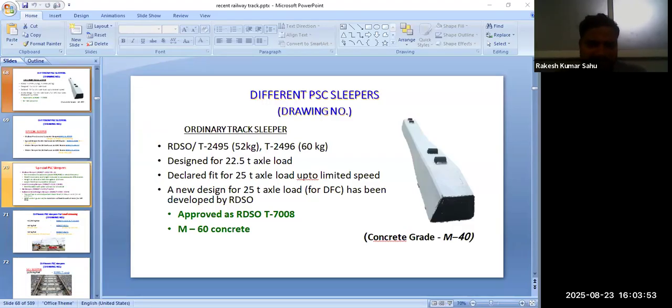So it provides heavy resistance and fewer weld and rail fractures. And its higher base area also provides an adequate factor of safety. Total stresses at rail seat and center section of PSC sleeper are brought down and its life improves.